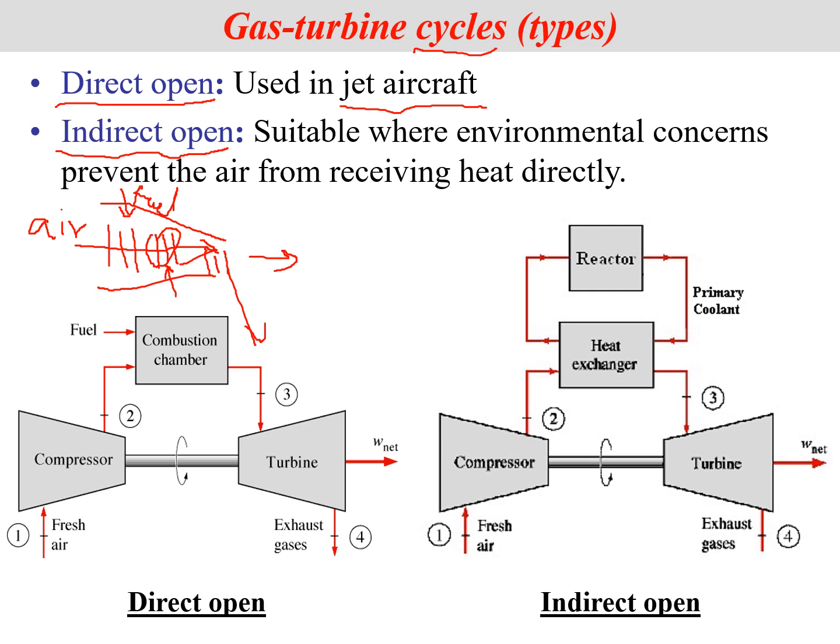So what you do is आप fresh air तो draw करते हैं, but you have the fuel burn in a separate compartment. ठीक है, और वो जो compartment है that just takes heat and gives the heat to this fresh air, and this fresh air gets hot and produces power in the turbine.